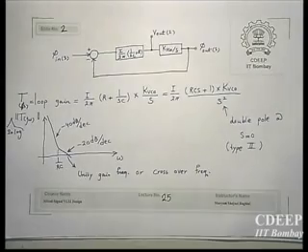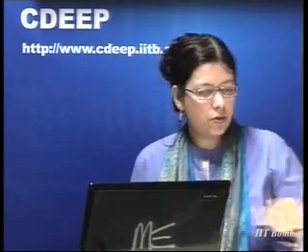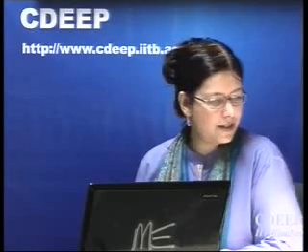It means that it's a stable state in the sense that you don't get any signal at the input of the phase comparator, or in fact at the output of the charge pump. I mean, in the block diagram, at the input of the phase difference. You don't get any signal, so you don't have any signal which creates that kind of energy generation inside the loop. This is my question to you, because I always think that this is some kind of instability, so this loop should not work with low frequencies.